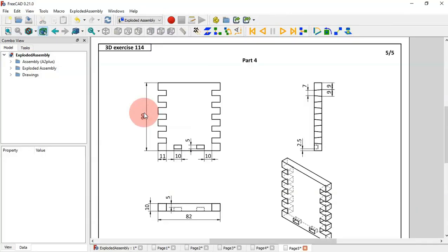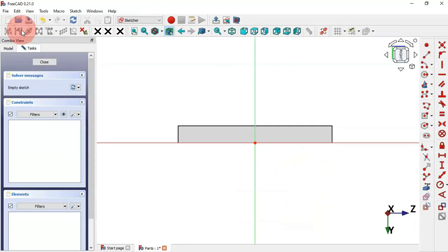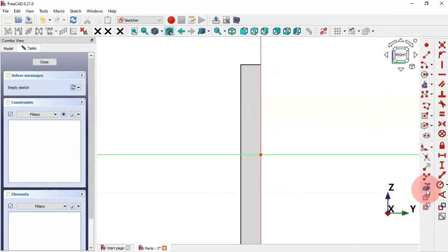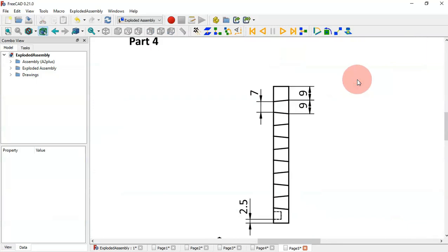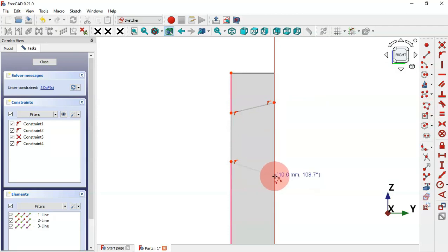And the next thing to do now is to create these pockets. So what you'll do here is select this face and create a new sketch. Okay, and now click on this icon here 2 times. Next, select the external geometry tool and extract this edge here. And now what we'll do in this sketch is draw this sketch here. So select the polyline tool, click on this vertical line, and on this edge here click again, and again on this line here and on this point here.